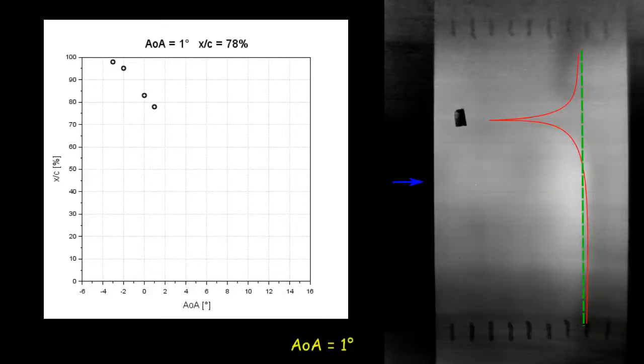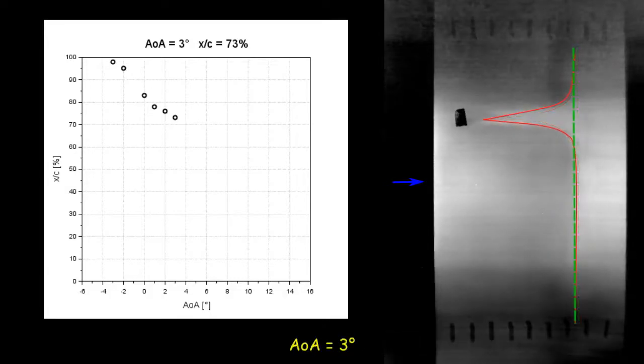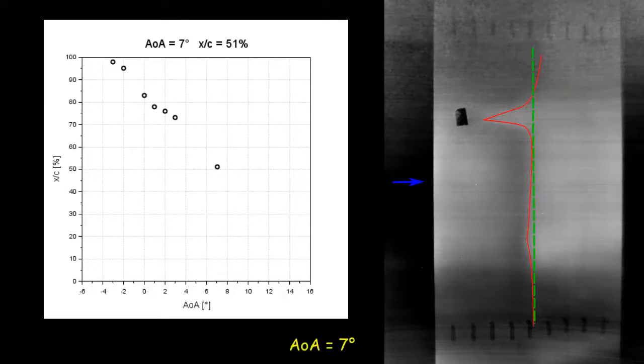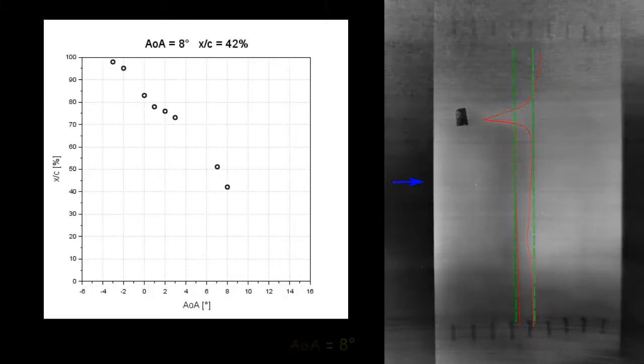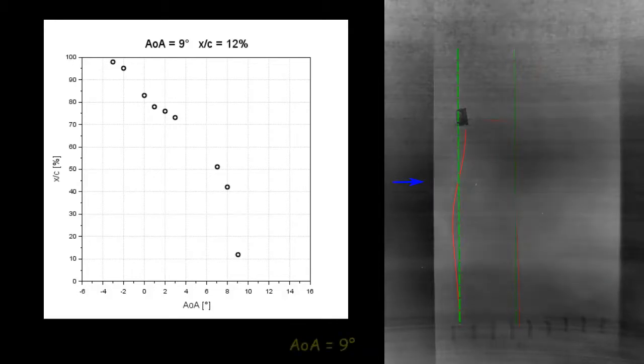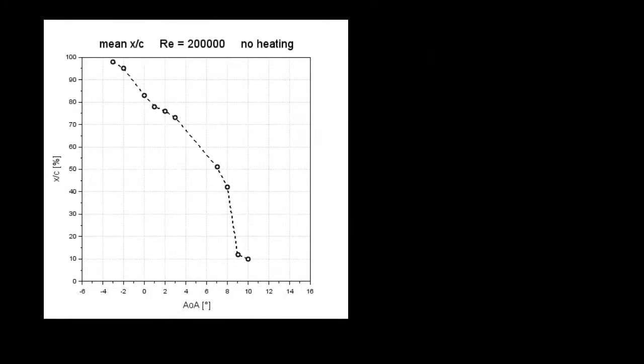This analysis is the simplest procedure, and it is still useful in times of large computer power and excellent image post-processing tools. This is because infrared images like these can become very hard to analyze by software, mainly because of noise and/or low contrast. However, a big advantage of using dedicated software is a span-wise transition location and not only a single mean value. For using software, one therefore would like to have an image with good contrast and low noise.